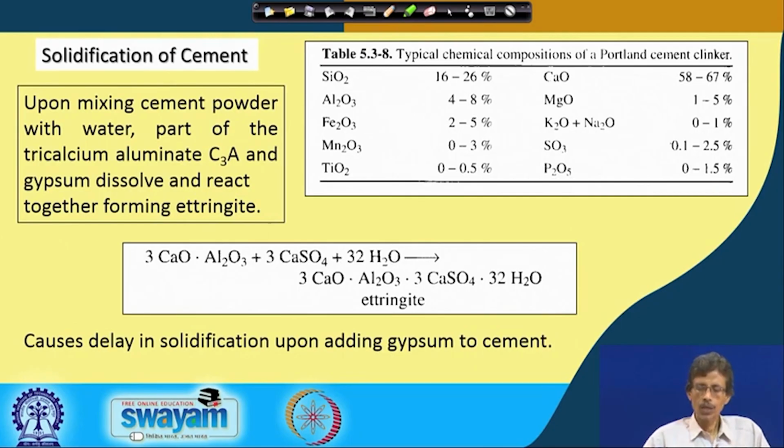That means the very slow hydration reaction, the kinetics of that particular slow reaction, can further be delayed with the addition of calcium sulfate. So, calcium sulfate addition will therefore be very useful. It will not compromise the quality or the strength of the cement material, the concrete that you will obtain from that particular cement, but the corresponding solidification process is different, and if your solidification is very fast, the strength will definitely be different.